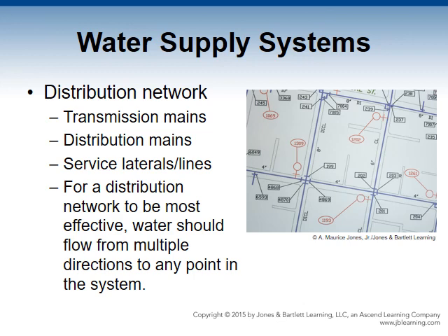From the water supply network, the water flows into a distribution network. The water main piping consists of transmission lines, distribution lines, and service lines. Transmission mains, made up of very large piping, transport a bulk of the water into an area of a city or a community. They can be many feet in diameter.